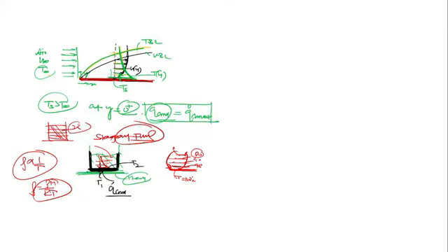But when we keep a heating rod or heating surface, now the bottom layer of the fluid is at a temperature of 100 degrees Celsius, and that causes a temperature gradient, and this temperature gradient causes a density gradient, and due to this density gradient there is a buoyancy effect, and due to this buoyancy force the high density fluid will come down and the low density fluid will rise, and that causes the convection current. Yes or no? So this convection current will create induced motion in the fluid.